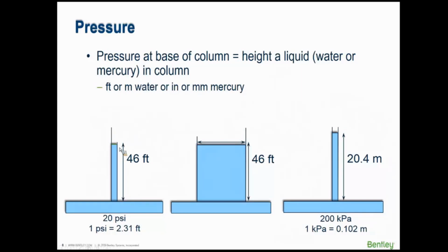But generally we talk about feet of pressure head. It's usually the way we talk about that. And people will say we've got 40 feet of head here or so. The conversion factor, for those of you working in North America, is 2.31 feet is 1 psi. Just memorize that number. It's something that comes up all the time when you're working with hydraulics. So if you don't have it memorized yet, memorize it now, because I find myself doing that conversion from feet of head into pressure units all the time. So it's just a good number to work with.